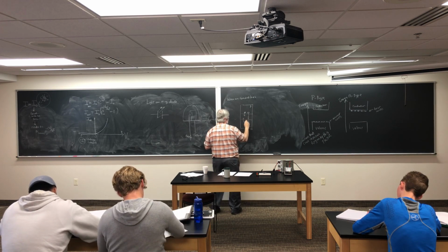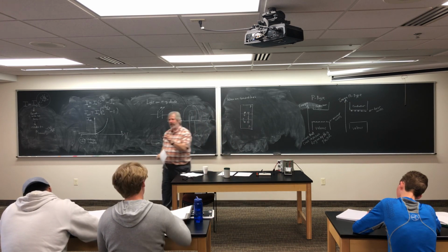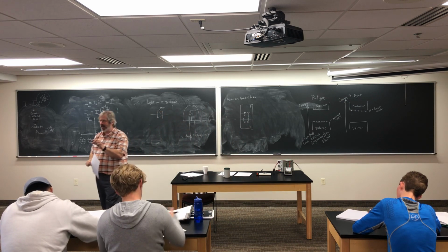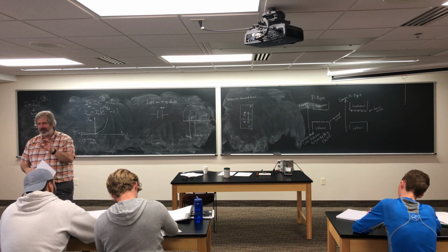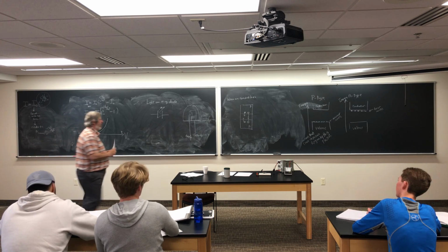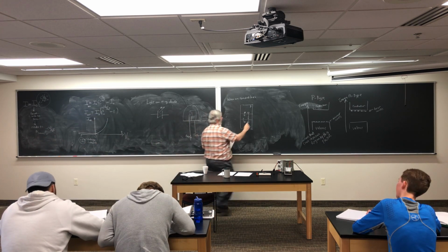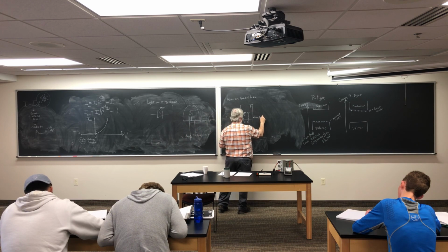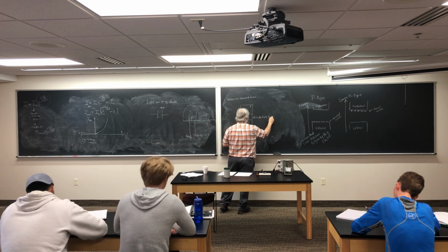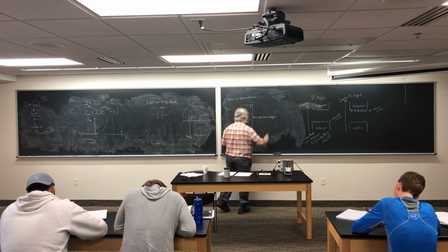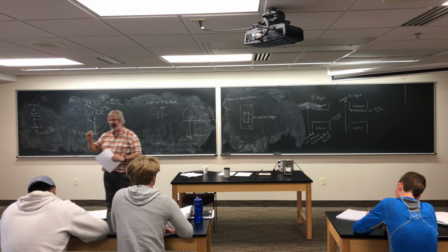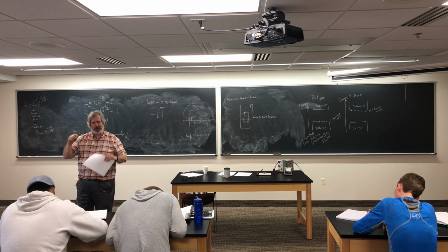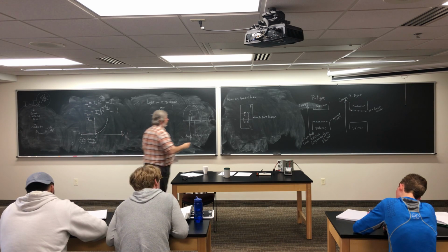And what we do is make the region in between the p-type and n-type a little thicker. They actually put in usually some other material that they call the active region. They just make it so that there's more chance that the electrons and holes will actually recombine before they cross all the way over. Okay?